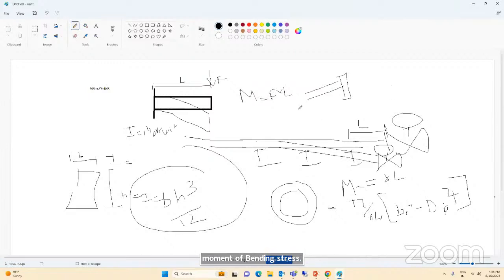Bending stress, yes, sigma. First, initially, we need to go to y. What is y? Y is the distance to the fiber. So, for example, if the center is elongated in this way, the outside diameter is fixed, right? So how much distance will it move? That is y. Y is equal to r₀, the outside radius. This radius will not change because I said this diameter is the same. So r₀.